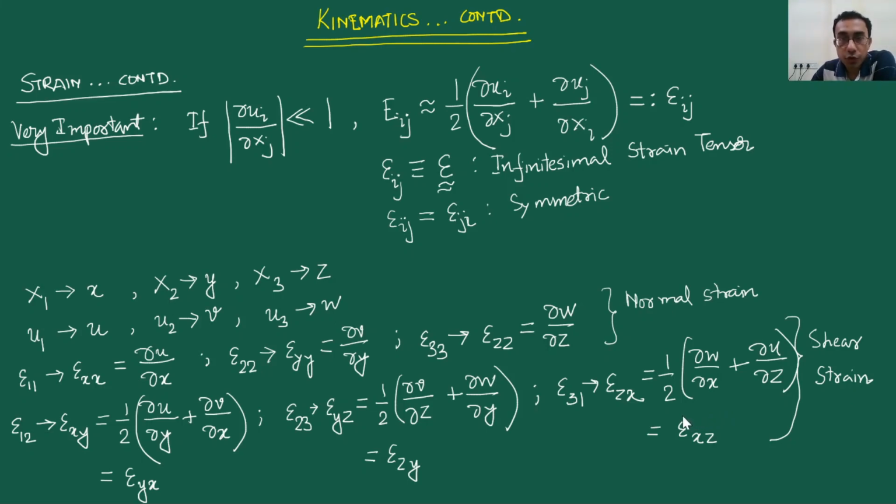you perhaps had learned in your first year, because I think some of you came across the term gamma xy or gamma yz in your first year mechanics books, and perhaps that was referred to as the shear strain. So there is no confusion actually. You can just note down that whatever we have defined like this here, the epsilon xy, that is nothing but half of gamma xy is equal to half of gamma yx.